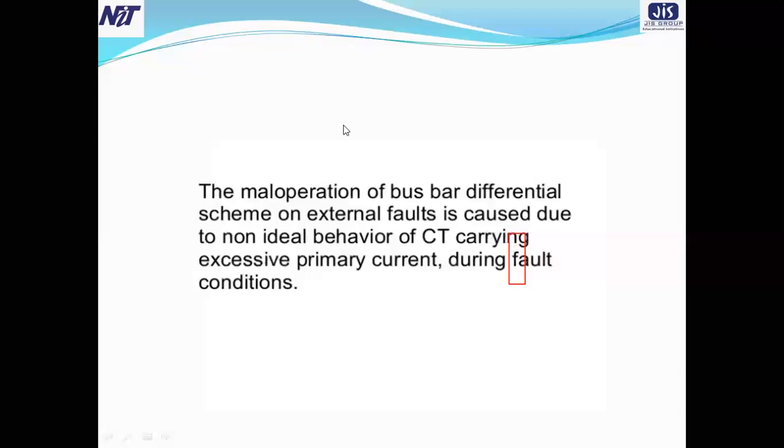Now look here, the maloperation of the busbar differential scheme on external faults is caused by non-ideal behavior of CTs carrying excessive primary current during fault conditions. Okay, so what is actually this?